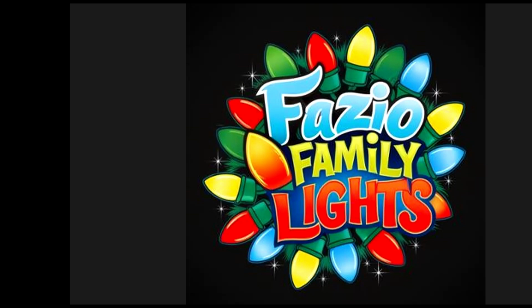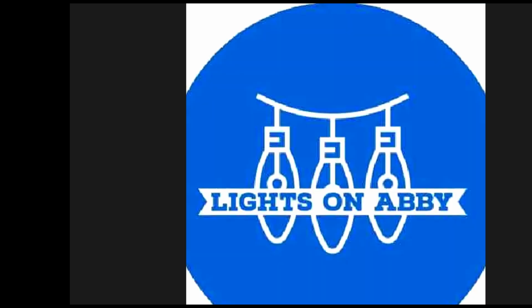Cheryl, is it related to the presentation? Yes. Okay, go ahead. We were wondering if they have a recommended number of pixels for seed bead pixels for power injection. Like on the 12 millimeter bullets, it's every 300 you inject power to cover 150. Is it the same on seed beads or is it different? No, it's about the same. Again, it depends on the pixel. The pixel amperage draw has gotten less over the last few years. It used to be 0.06.